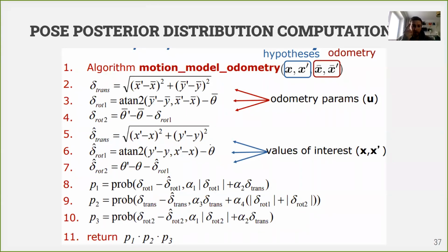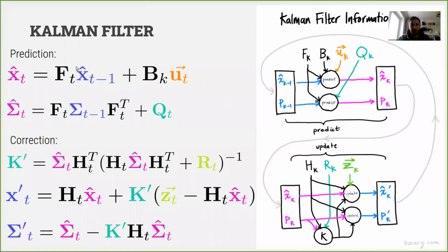The first one will be on the Kalman filter, and it will be really simple. You will have the whole Kalman filter programmed, and you will just need to fill in the matrices which represent the system state, control signals, and the measurement model H, depending on the description.